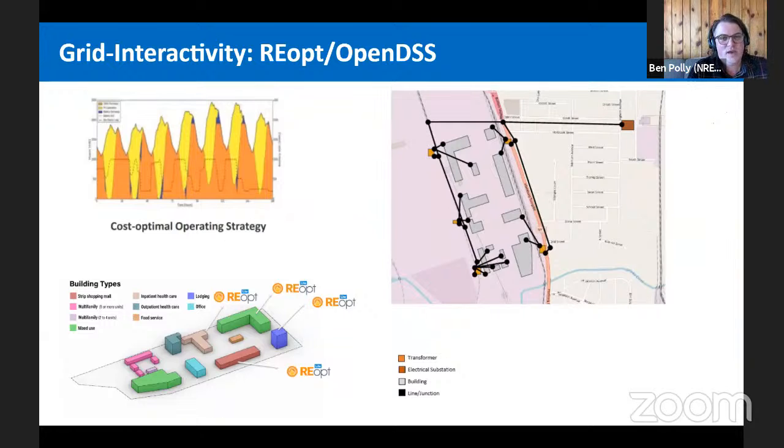So what we've done is, if an electric distribution feeder is specified within the URBANopt GeoJSON file, which is visualized on the right there, and then connected to buildings, we've automated a lot of the workflows to take the building simulation results that come out of URBANopt and, utilizing a tool called Ditto, translate them into OpenDSS models so that you can then understand the potential impacts on the distribution system.